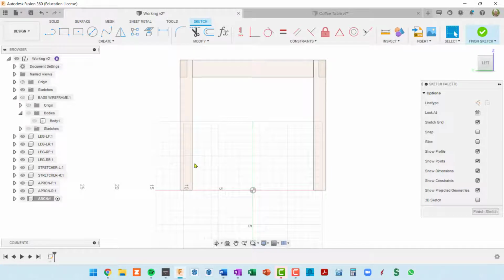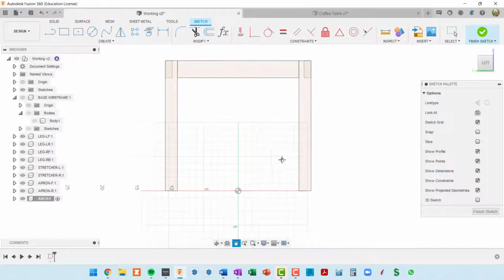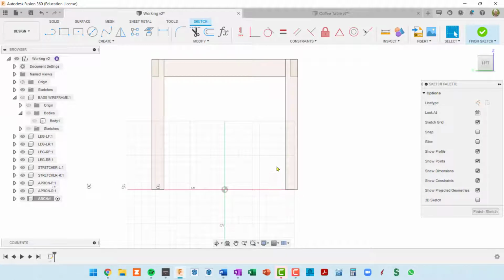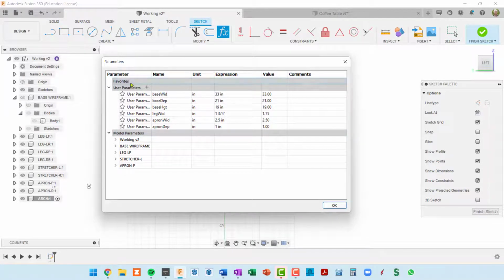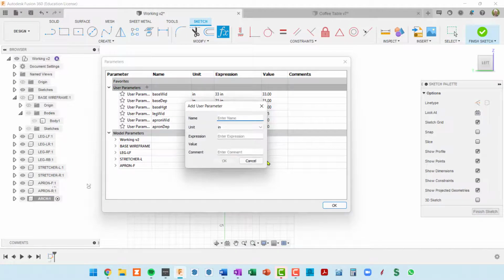Now this piece is going to be up in space somewhere, and there's nothing to snap to here. So we're actually going to have a parameter that defines how far off the ground the bottom of this arch starts. So let me go into my parameters, and I might as well do all the arch parameters at once. So arch width is going to initially be set to 3 3/4.